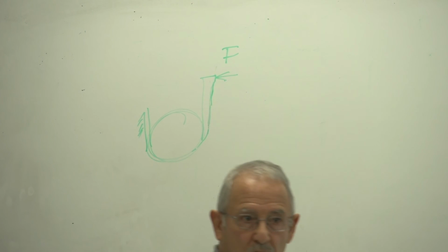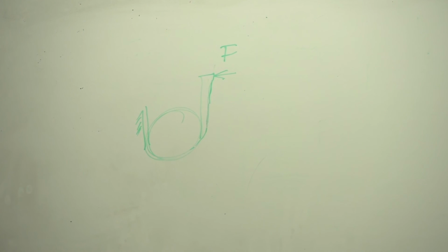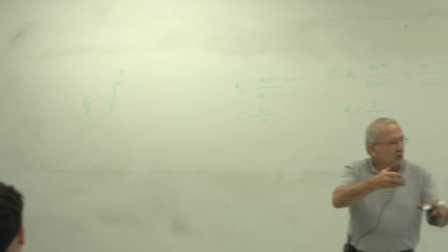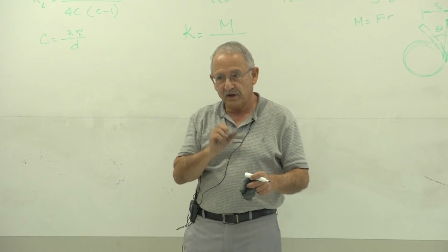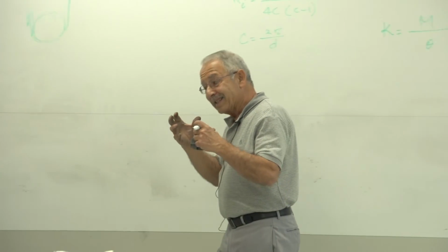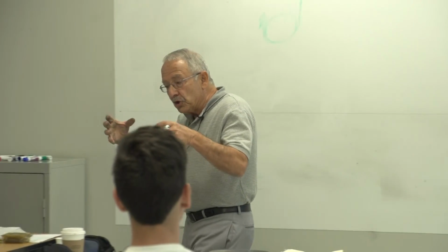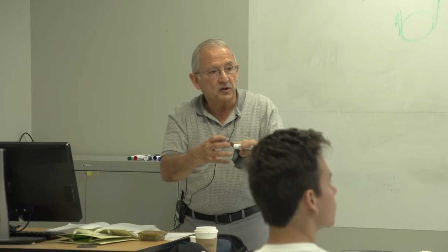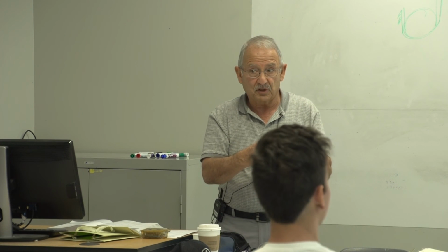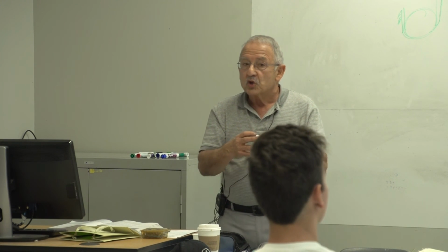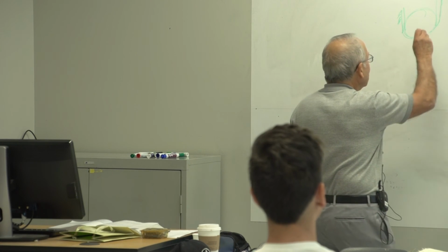It deforms by rotation. So the number of coils increases. If you started with 1 coil, maybe it's now 1.5 coils, 1.25 coils, what have you. As that happens, the internal diameter of the spring also decreases, becomes smaller. So if you have a mandrel here,